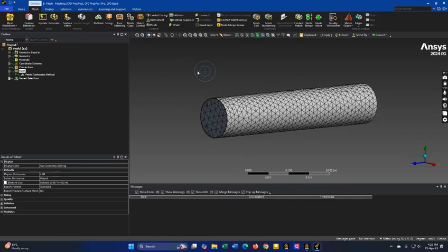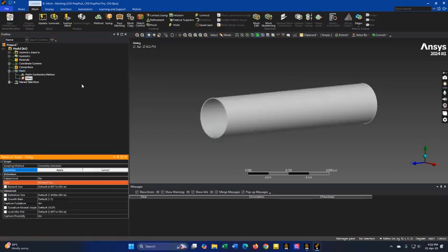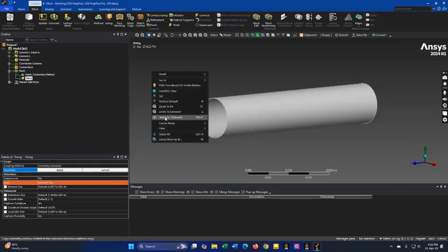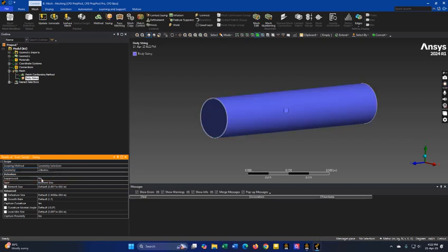While giving a body sizing, it will be after the whole body, so make sure that you select the whole body while sizing. Go to sizing and select all, while keeping in mind that this body part is selected, not solid, not surface, not point, not edge, only this body part. Alright, now apply it. You should see again two bodies, and change the element size to